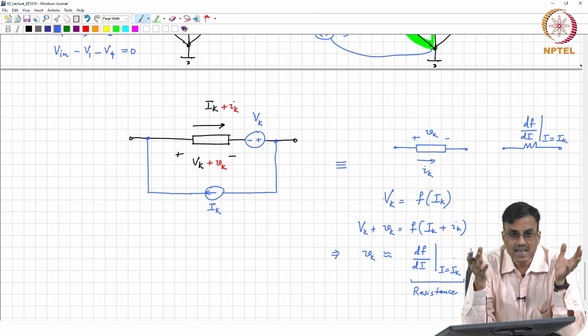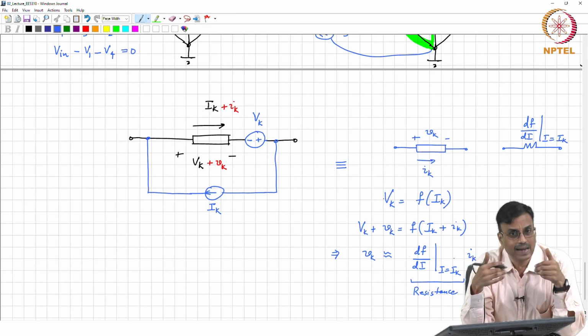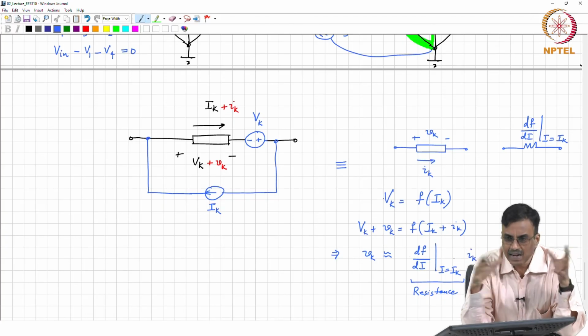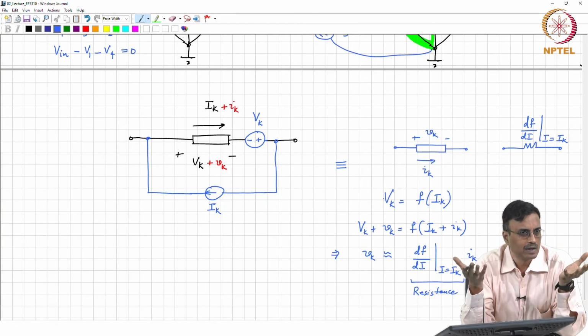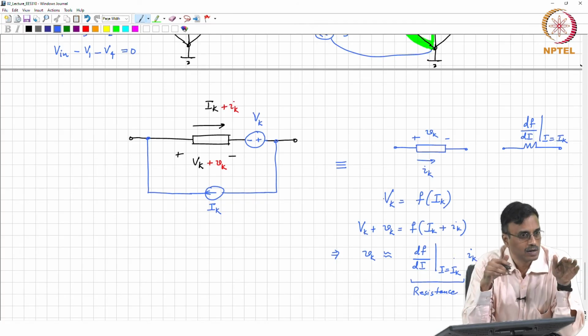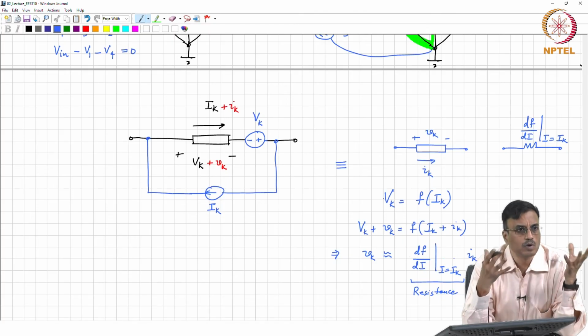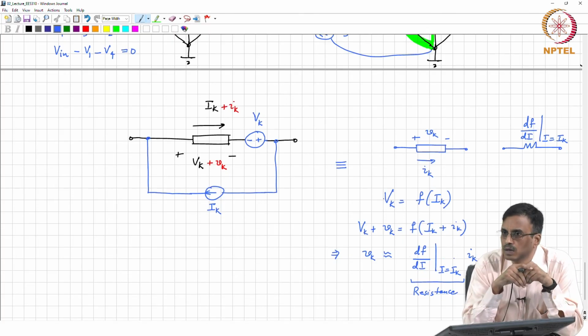Now, the linear network may take time to evaluate, but if the network is big, we know that the linear network will be big, but we know how to evaluate it. It may take time, but we can do it. Whereas, with the original operating point calculation, it may simply not be possible analytically. You have to go for numerical techniques. Does this make sense?